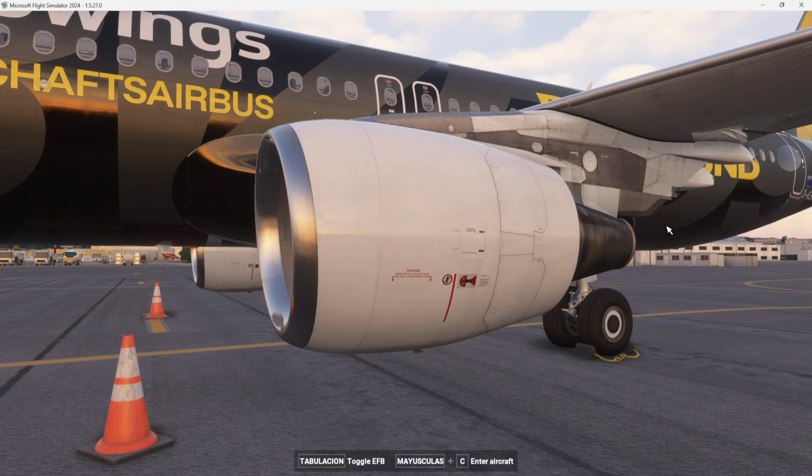We need it to run the engine, for the stability of the engine, and also to power the high pressure compressor, low pressure compressor, and the accessories of the engine. So the core is going to produce energy to spin the fan and compressors and all the things.